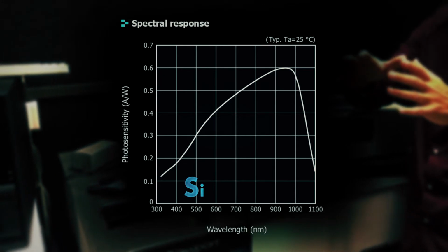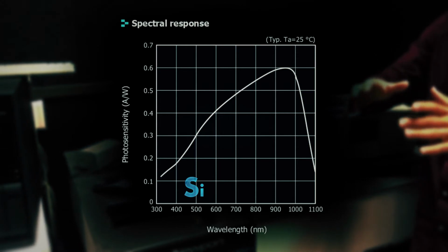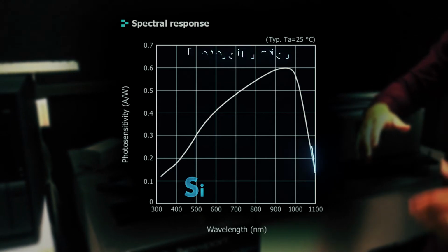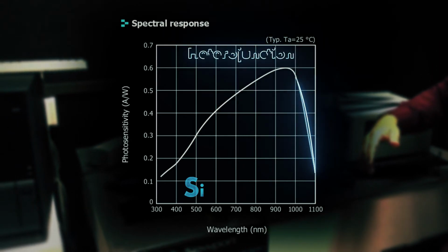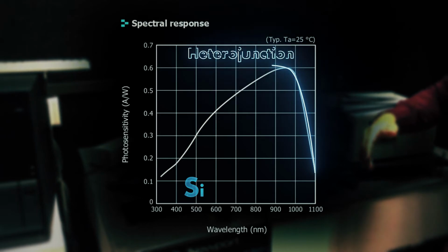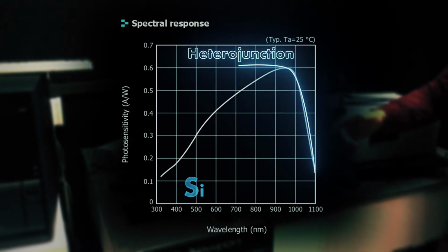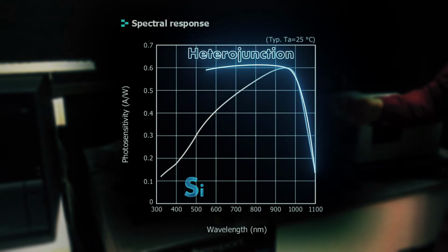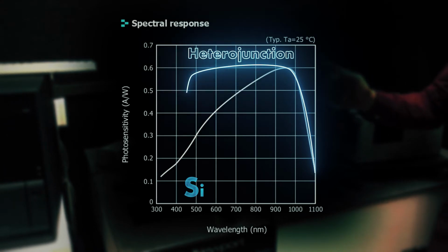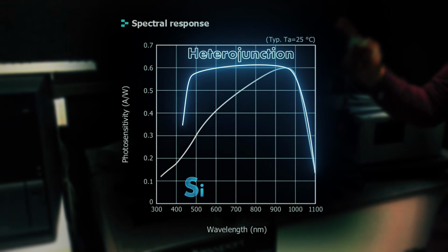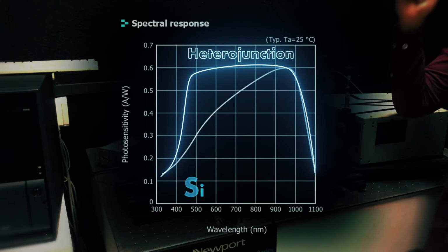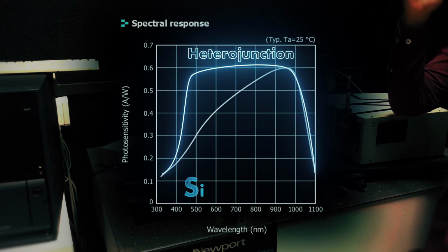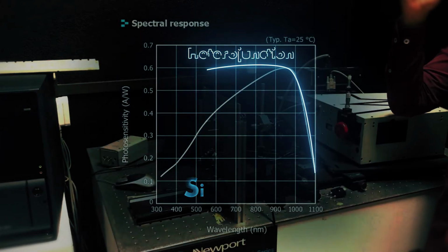In a heterojunction photodetector, the N and P sides are composed of a material with an elevated energy gap value and separated by an intrinsic layer. This generates a trapezial-shaped response, since the radiation starts to be absorbed in the intrinsic layer with the smallest energy gap and maintains a relatively constant absorption. With the increasing energy, the absorption happens each time closer to the interface of the intrinsic layer, until the responsivity decreases abruptly, because we get to an energy value corresponding to the gap of the doped area, so the absorption happens there and is diminished for the aforementioned reasons.